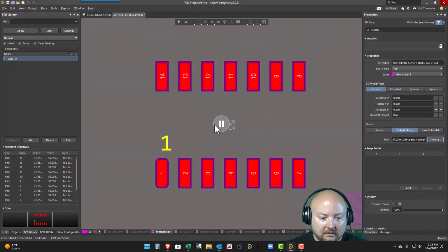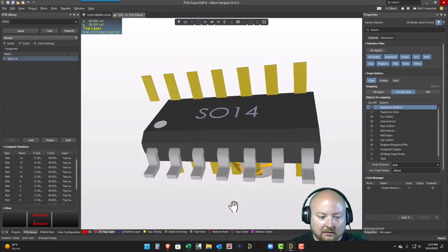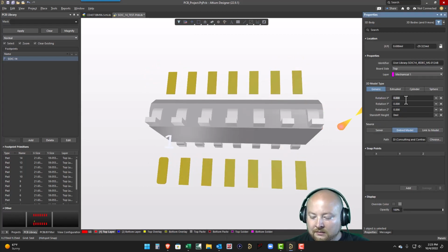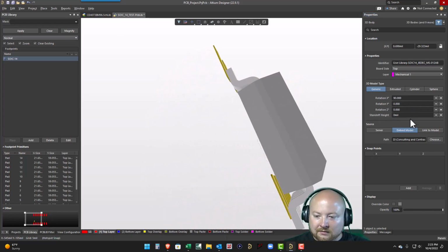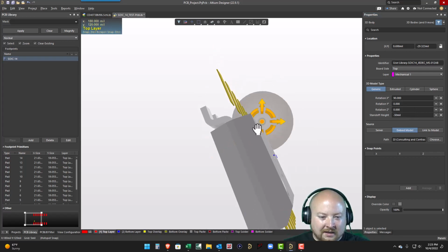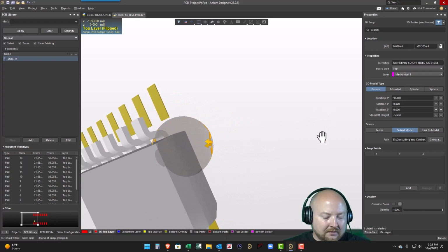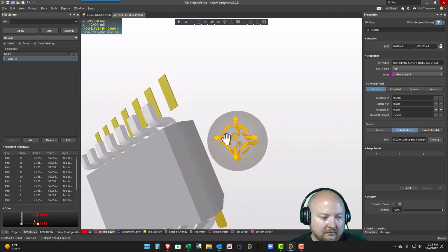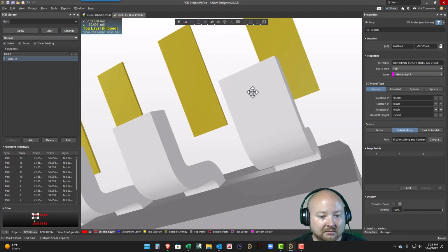Open. Okay, and it's obviously rotated. A lot of them come in this way, so you just click on it and then rotate it to where it needs to be. And in some cases, parts are not on the same plane that they need to be, the surface of the board. So you can either just play with the standoff height until you get it right, or you can find a part that's supposed to be flat on the surface of the board.